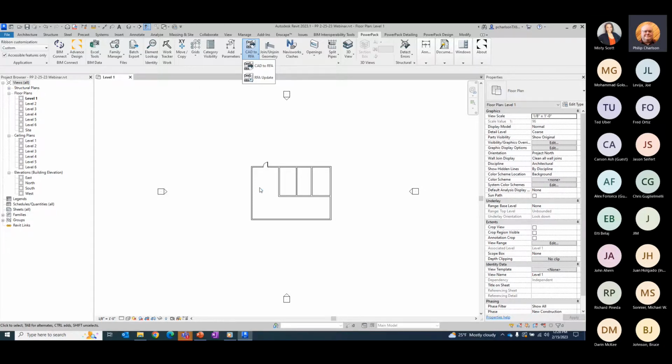So let's say it's a light fixture that you go in and drop into place. Okay, well, I'd probably set it to a lighting fixture family. So when I select it as a family, I can save it as a Revit family. It'll apply the electrical content, so all the different parameters relating to light fixtures.